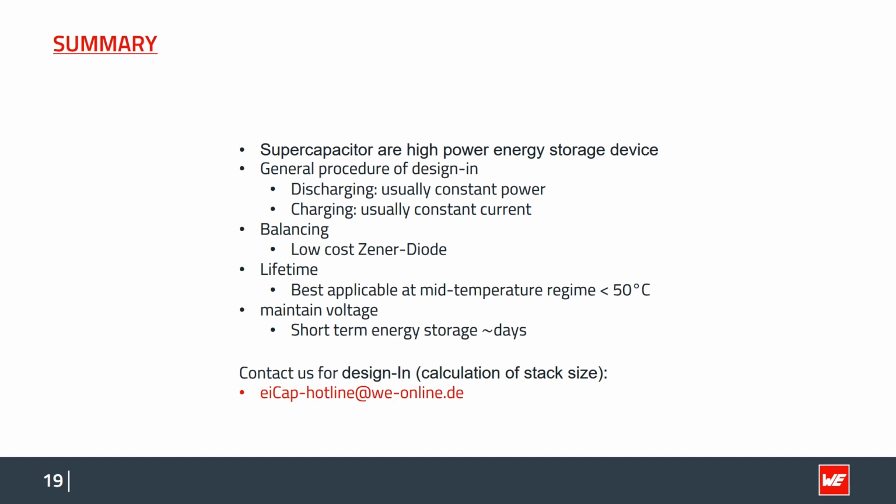In summary, what is it that you should take home? Supercapacitors are high power energy storage devices. Concerning the procedure of the design-in, the discharging is very often under constant power. The charging usually is under constant current.